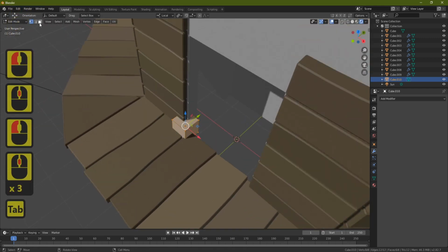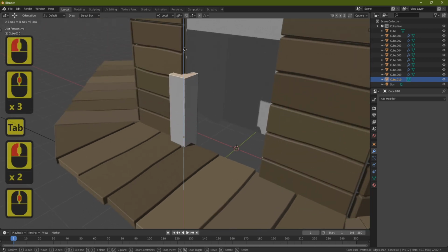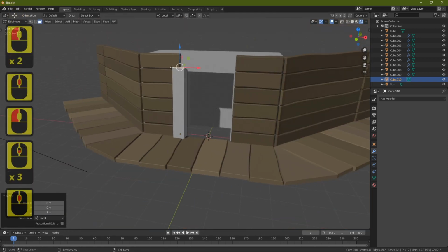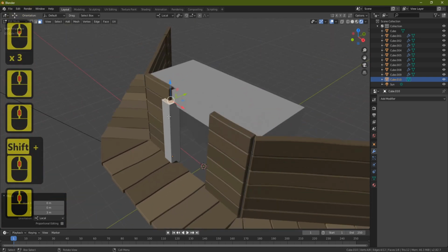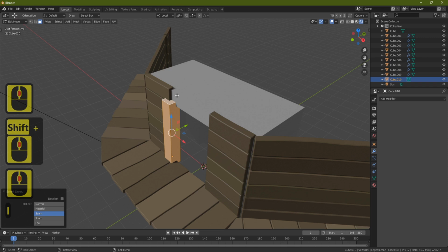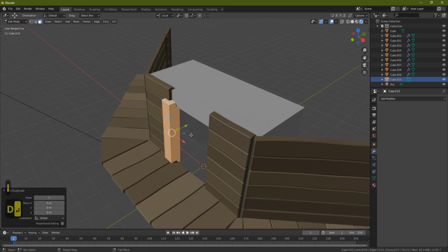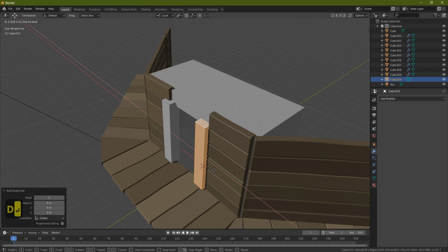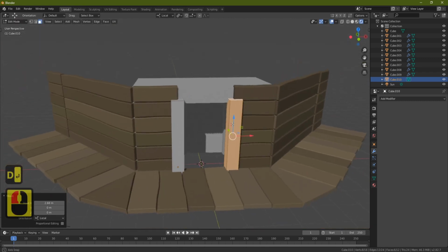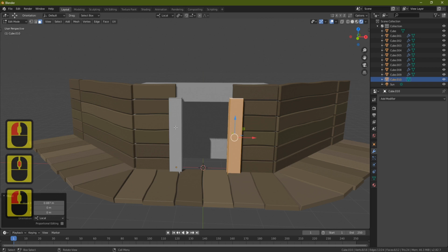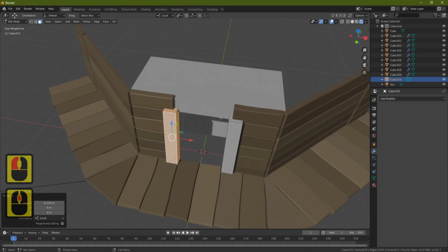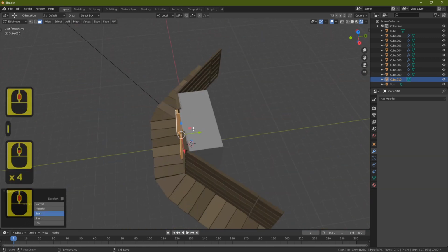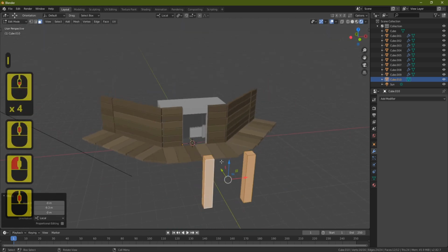You want it relatively chunky, so let's go to Face Select. And you're going to have another one going across here, so just make sure that you've got it as chunky as you want it, and I think that's going to be fine. And what we'll do is we'll make 2 of these, so Shift D, Enter, bring it over to around about the same place as the other one. I'm just going to bring them both across a little bit more just to make sure that I've got enough room for my saloon doors. I don't want to make sure they're too small. Now let's grab them both, pull them out, and let's start work on these.